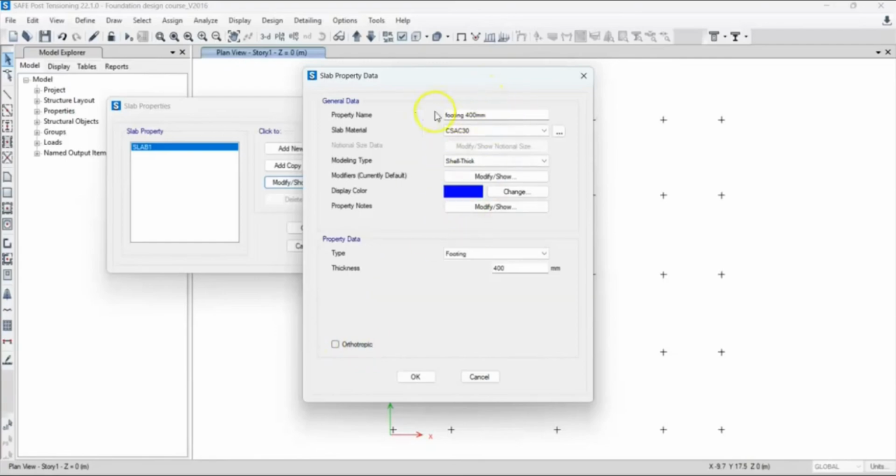But for our isolated footing, you need to leave this box unchecked, because for footing, we know that our concrete has the same stiffness in both directions. It behaves with exactly the same stiffness in all directions, because a solid concrete footing is what we call an isotropic member.